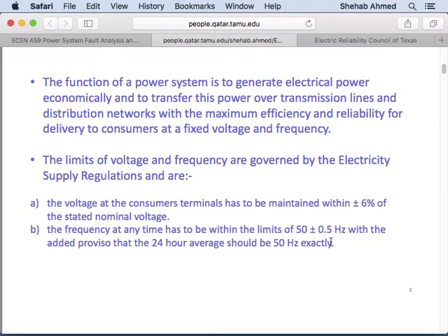But luckily, what's happening in generators is, as soon as you spin it and you create this time-varying magnetic field and the voltage and the corresponding current, a force is developed to oppose the input force. So then we have a steady state condition. The force coming in is equal to the force coming out plus the losses. Right? That's steady state.